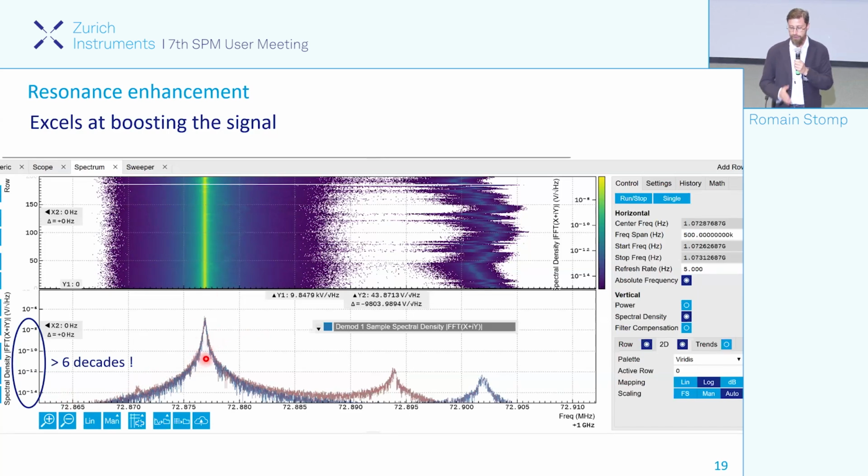At the same time, it's nice to look at this, an FFT of the demodulated output. So that's not just the values that you get from a sweep. Before I was showing the SNR with the Gaussian distribution, which was basically just data as a function of time. Now if you take this data and make an FFT of it, this is what you get, for a certain bandwidth. So that means that you can also look at how the signal behaves with respect to some other resonance, especially if you're doing some multi-frequency.